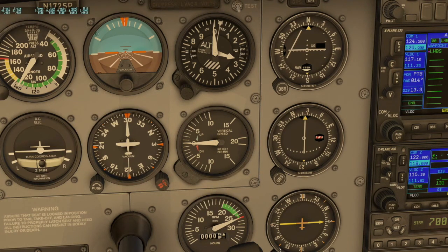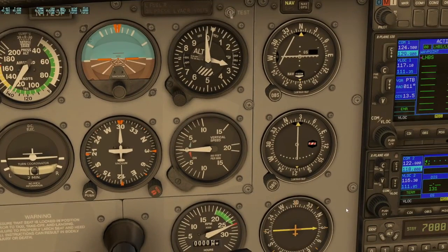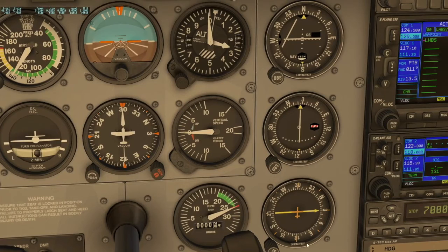Again, this is following the steps that we've learned. You need to memorize the steps that I've shown you in the PowerPoint presentation a little while ago, how to intercept inbound radials. Once you understand these, it's very simple to implement them if you use the ADF or any one of the dials in the plane that you're not currently using or not tuned into anything, as a guide on how to navigate. We said we were initially at the 022 radial, and then we're going to go up this way until we hit the 000 radial. Then we're going to turn left this way. What is this direction? Here it is, 210.